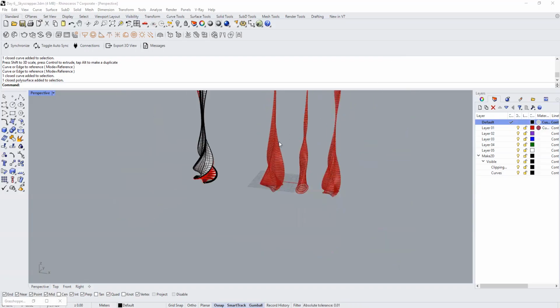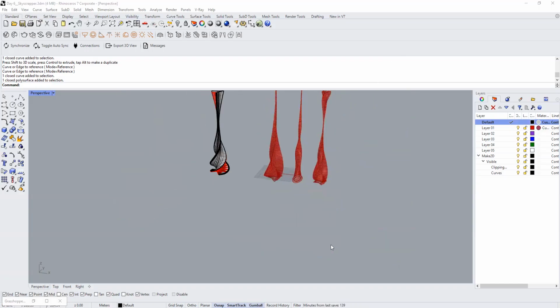And how would you do a split? You would need two things. One is the object to split. We have the tower, it is the object to split. You also need a cutting curve for that. How would you get a cutting curve in Rhino to do a split? We can create a new one.